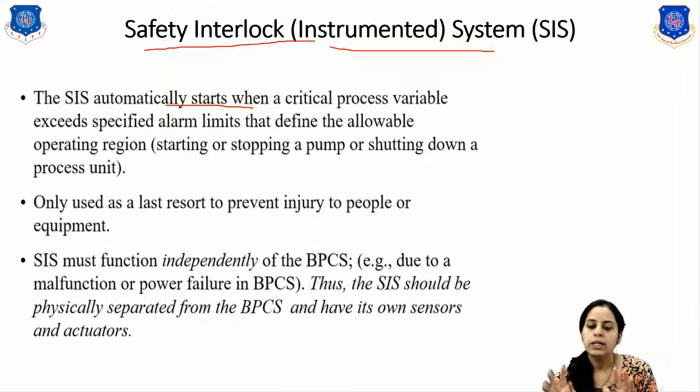Basically the SIS must function independently of the BPCS, so that a malfunction or power failure in the BPCS does not affect it. Thus the SIS should be physically separated from the BPCS and have its own sensors and actuators.